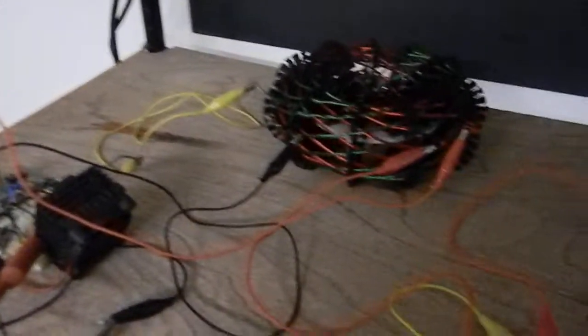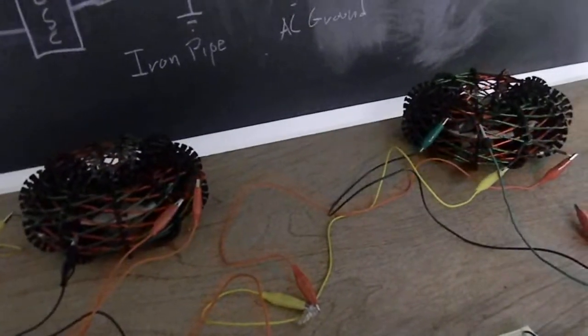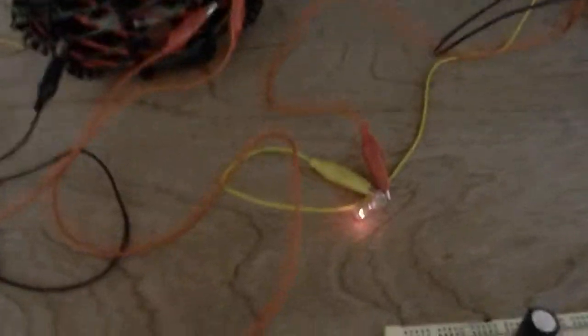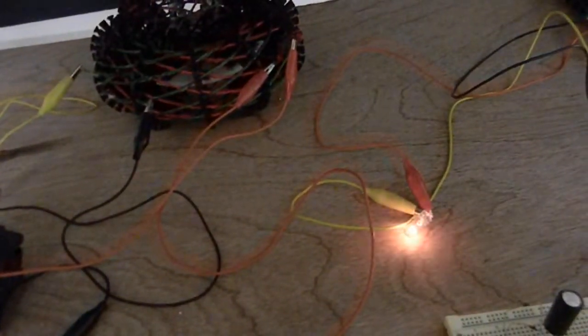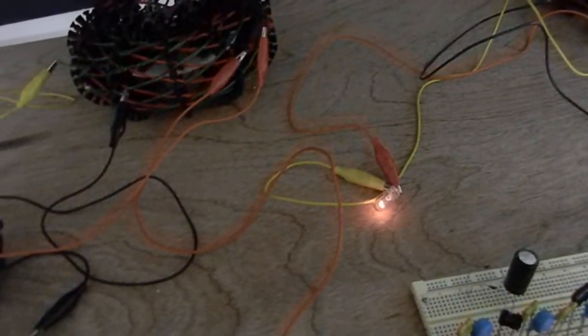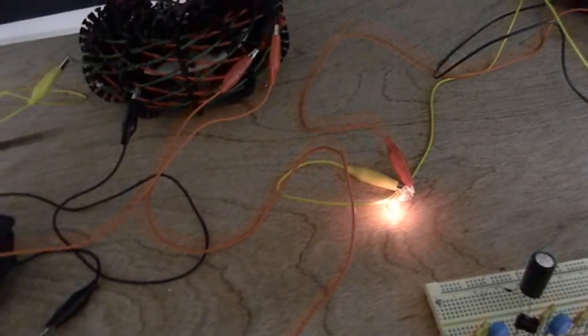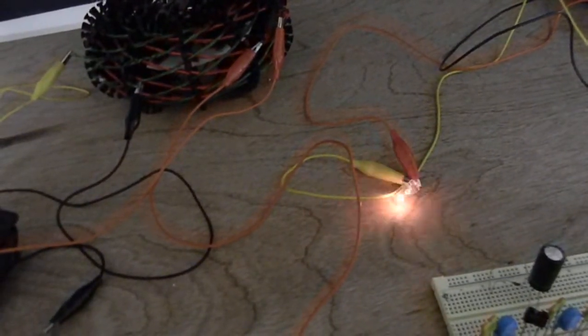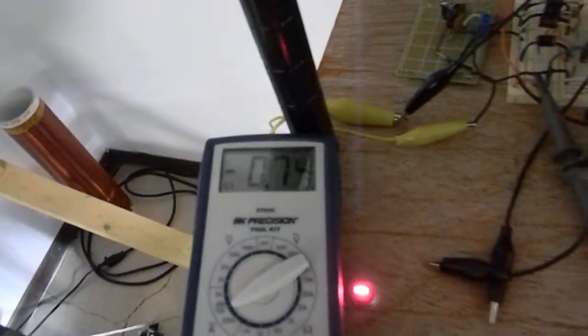Well, check this out. So now we're going to use this schematic here, and we got 12.7 nanofarads of capacitance here. It's like all my mica capacitors there. And we'll turn it on, and we got light, and we'll turn it down. We're at that big frequency, or the really high frequency to drive that. So we'll tune it down. We'll find that there's another resonant spot. So now we're down to 0.7.